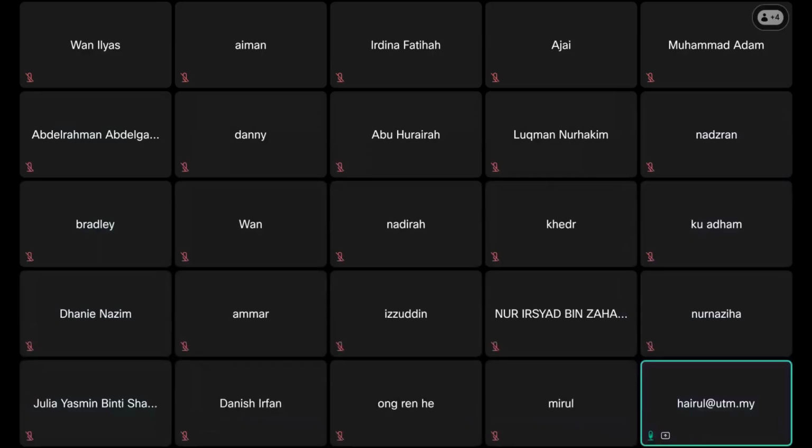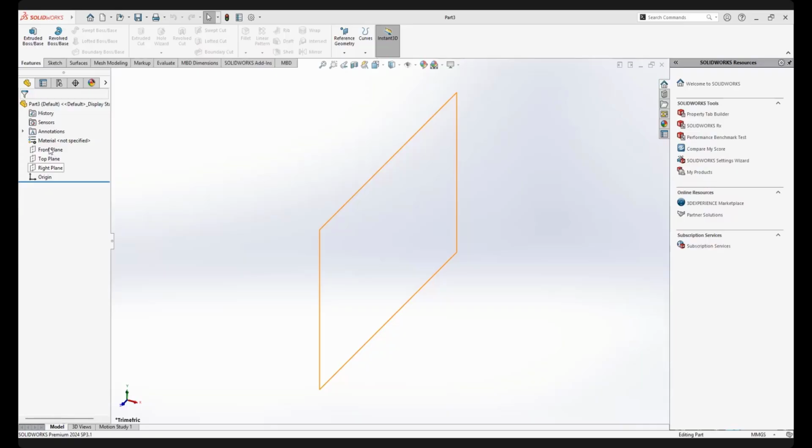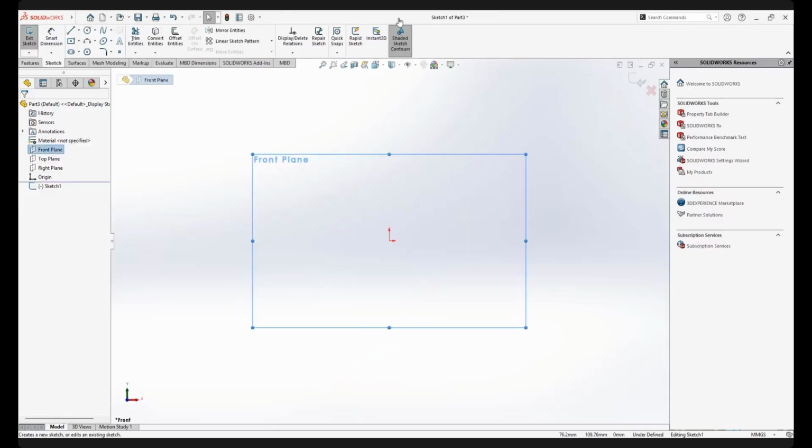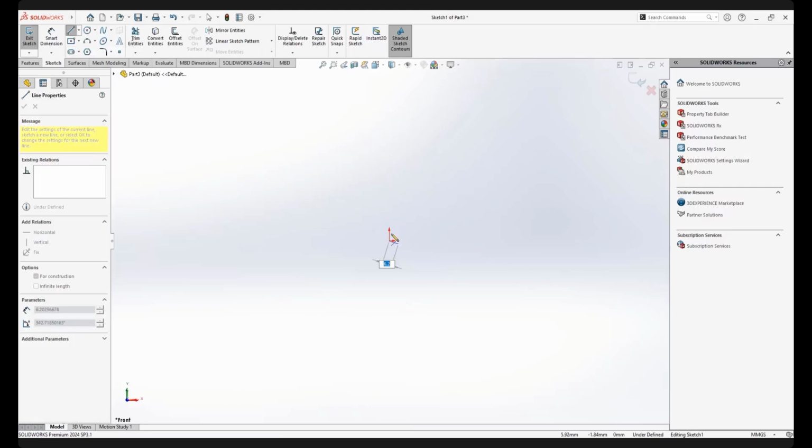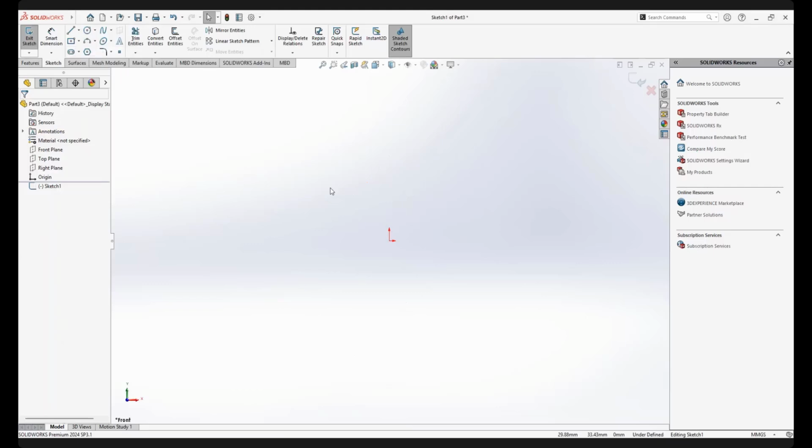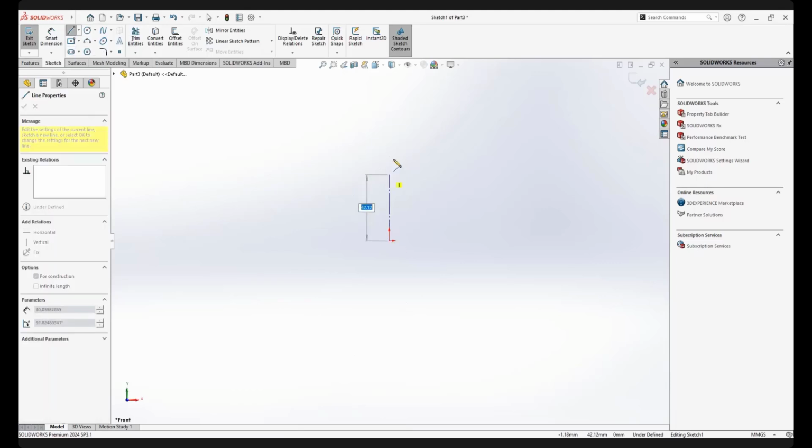All right. Okay, now I'm back to Solidworks. I already set the unit MMGS. So I will do it at the front plane. On the front plane, if you look at the question, you must start with the center line. The center line is your axis of revolution since you want to create that hollow cylinder. Remember guys, some students make a mistake. When you draw a line, start at the origin. The axis of revolution, center line, at the origin, vertical up,